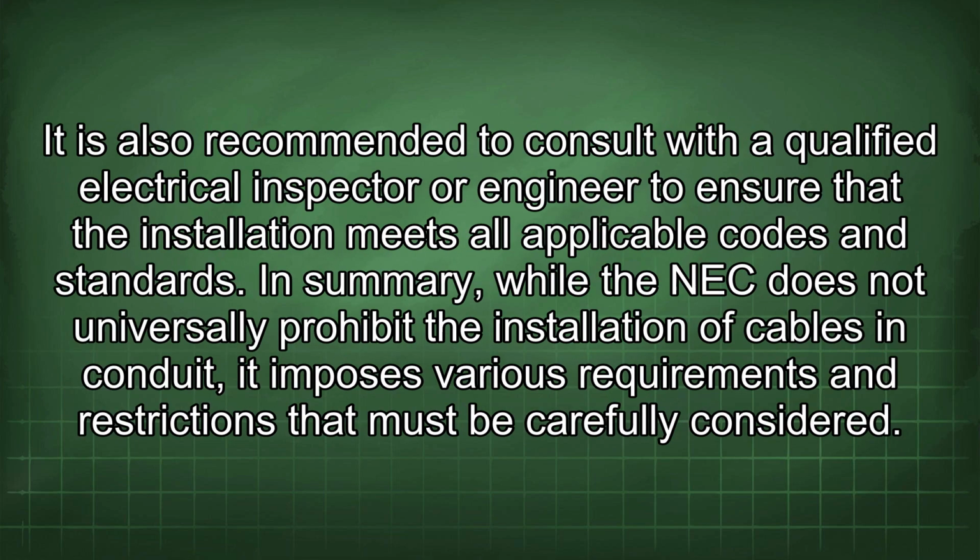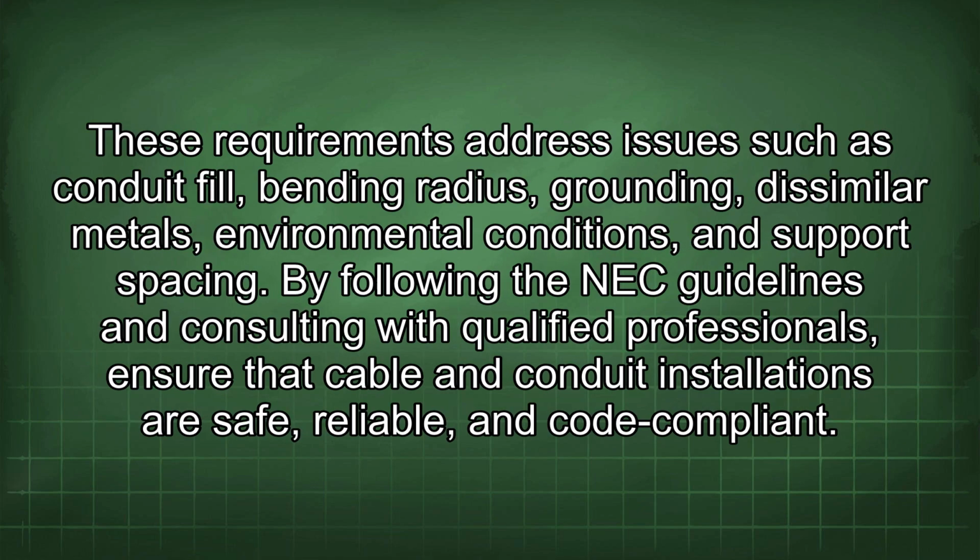It is also recommended to consult with a qualified electrical inspector or engineer to ensure that the installation meets all applicable codes and standards. In summary, while the NEC does not universally prohibit the installation of cables and conduit, it imposes various requirements and restrictions that must be carefully considered. These requirements address issues such as conduit fill, bending radius, grounding to similar metals, environmental conditions, and support spacing. By following the NEC guidelines and consulting with qualified professionals, ensure that cable and conduit installations are safe, reliable, and